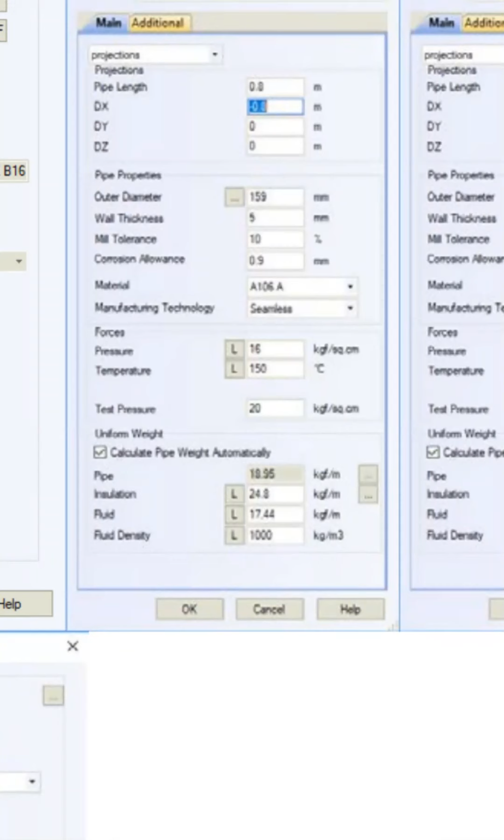The reason being that if an incident occurs or an abnormal situation comes up, your pipe will be able to withstand that excess temperature or pressure. But if you model with a lower test temperature and pressure, then your model will appear right, but in real life, when the pipe goes to a temperature or a pressure greater than the calculated pressure, your pipe will be deformed. That's why we need to take cognizance of the temperature and pressure we use during testing. Okay, so get to the next slide.